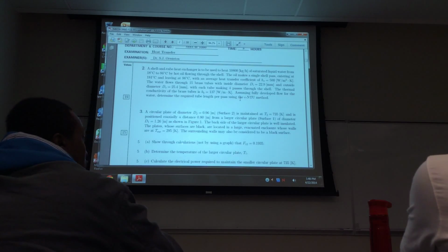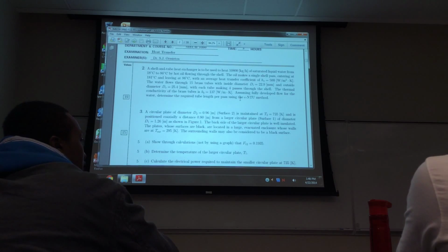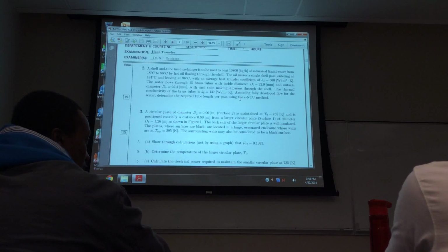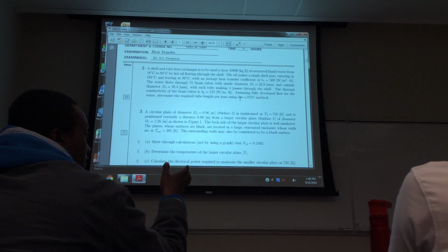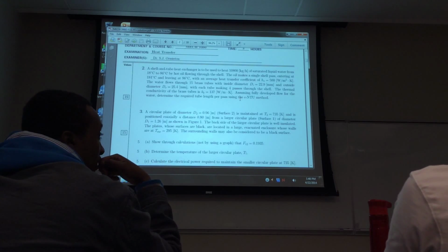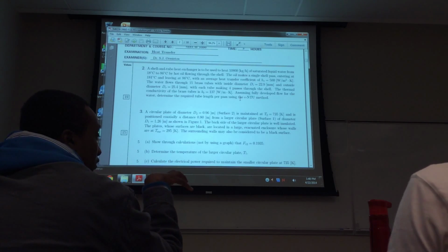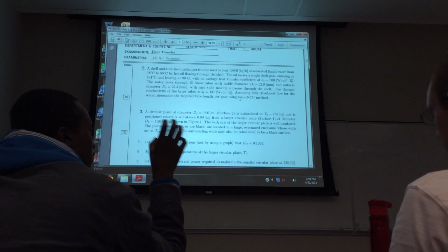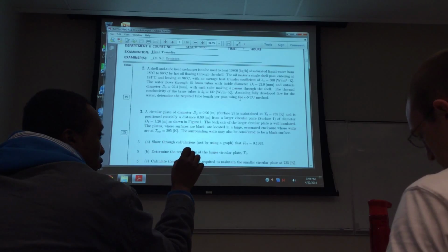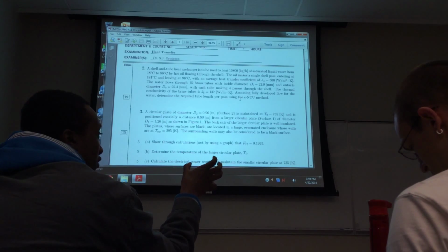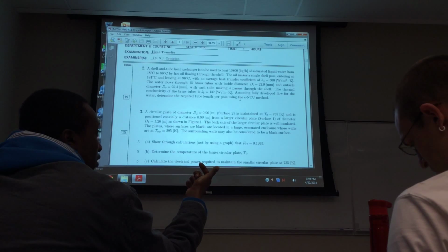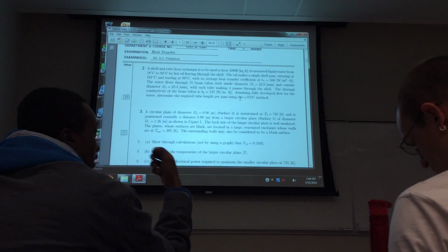So for the fin equation, like when you're saying derive the fin equation, in your notes you derive it when it's infinitely long. Well, that's in the example, in the textbook, for the infinitely long case. Right. So they're all the same up to when you get that second order differential equation, and now you have to use the boundary condition, and you have either the convective tip or the insulated tip or the temperature specified tip.